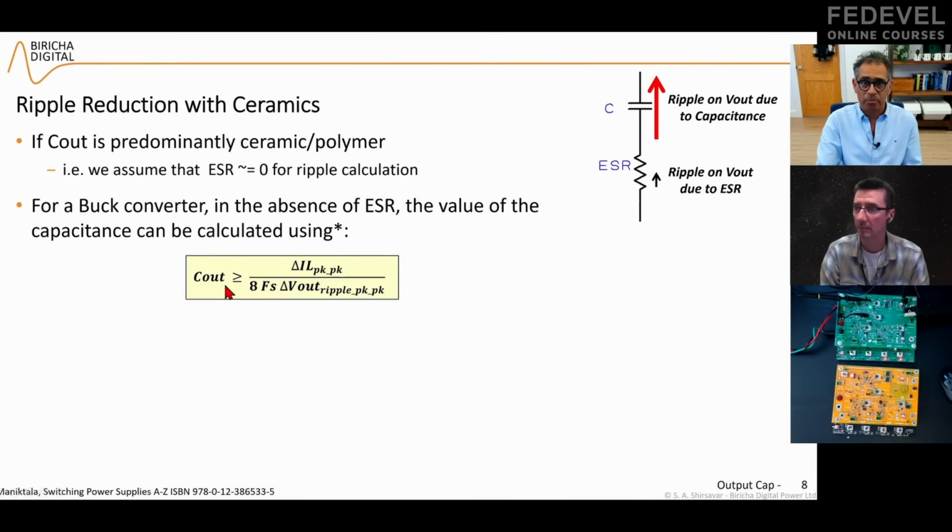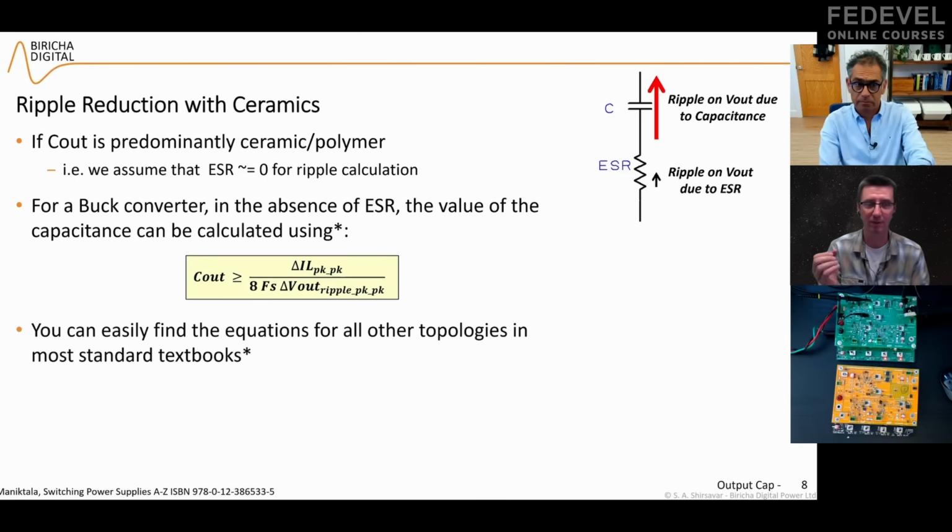I can calculate my C out, and that's my second calculation. Then I compare that with the calculation that we did just a few minutes ago, 150 microfarad, and whichever is bigger is my worst case. Right? That's what I wanted to ask. So basically, this doesn't mean you need 2 different capacitors. We are talking about one capacitor. We are just trying to find out what the value is, and which one is the bigger one. That's the one we will use.